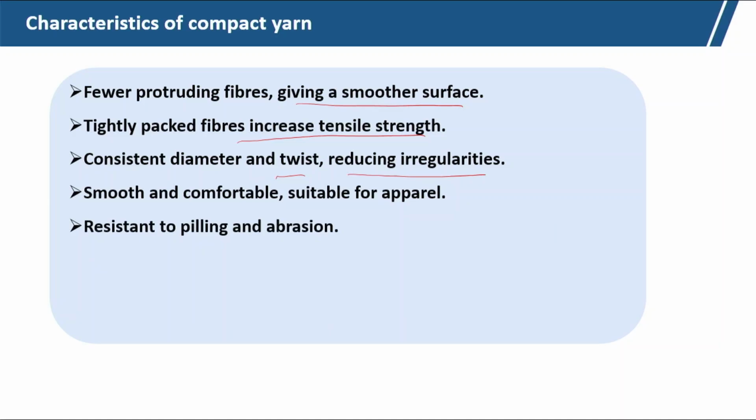It is resistant to peeling and abrasion, because any peeling starts from the protruding fibers. So, due to the rubbing action, the protruding fibers get rolled and form micropeel, and gradually the size of this micropeel increases, and that forms the visible peel.